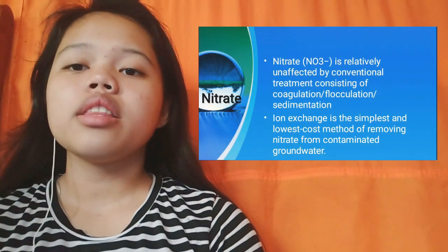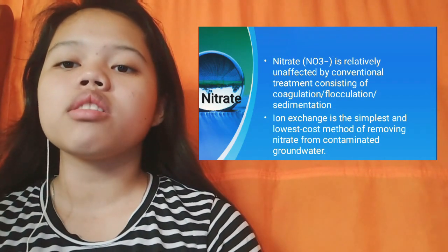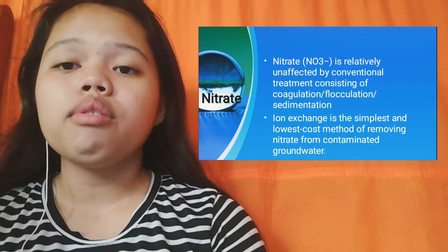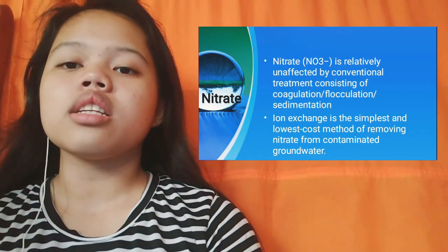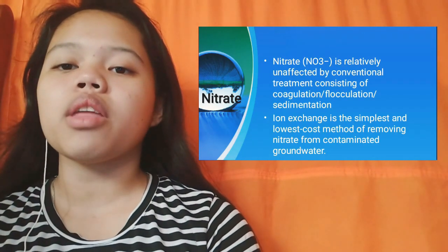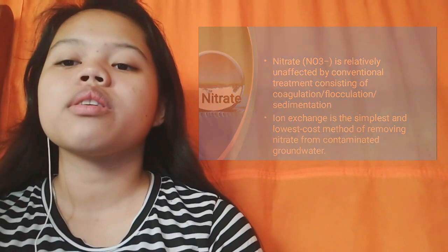Nitrate. Nitrate is relatively unaffected by conventional treatment consisting of coagulation, flocculation, and sedimentation. Ion exchange is the simplest and lowest cost method of removing nitrate from contaminated groundwater.